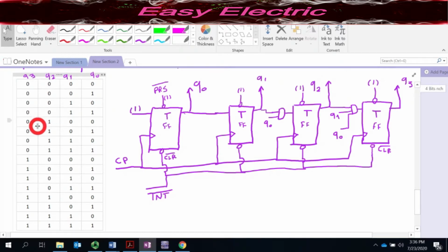So see here, Q0 and Q2 actually toggle from 0 to 1. At that time Q1 with actually Q0 is 1. So that means it should be right if you connect the AND of Q0 and Q1 to the third one. See here, it is 1 and 1, Q0 and Q1 is 1, so toggle happens, right? So then again, all of them are on hold.